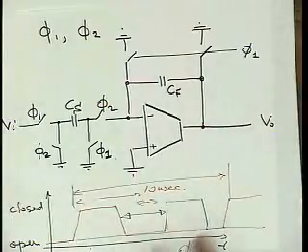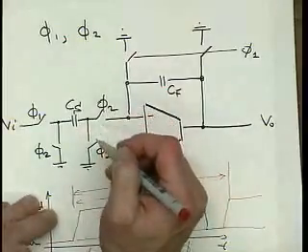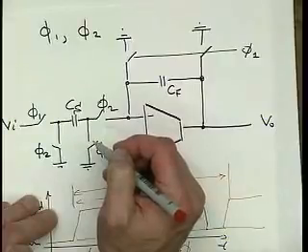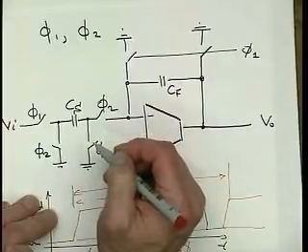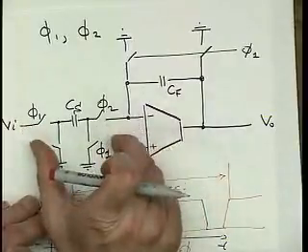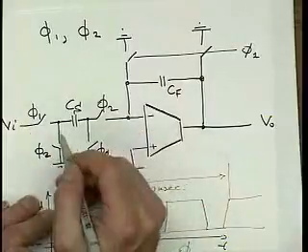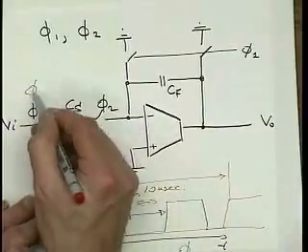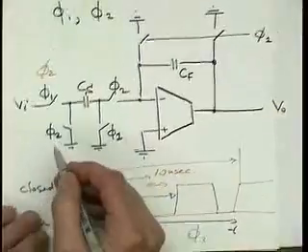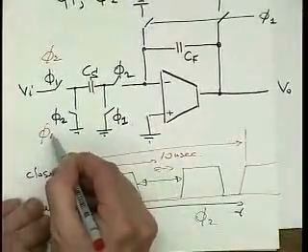We can build amplifier feedback stages that are single-ended and give us positive gain if we like that for some reason. If we want to have a negative gain, no big deal. We just use a slightly different switch arrangement where, let's say, this one is phase 2 and this one phase 1, right?